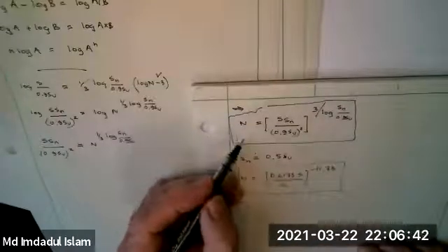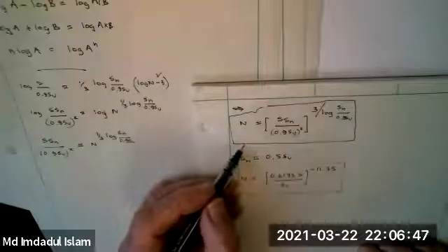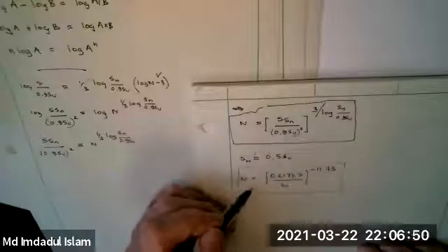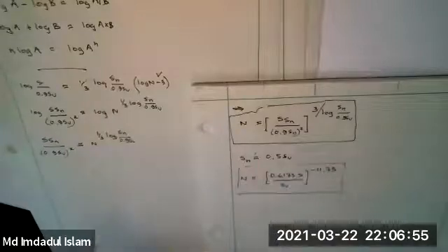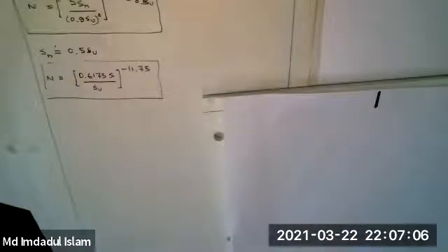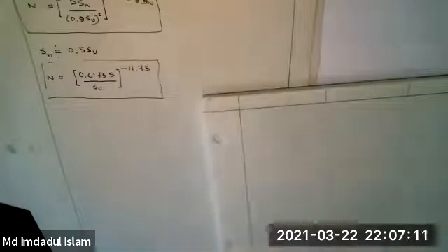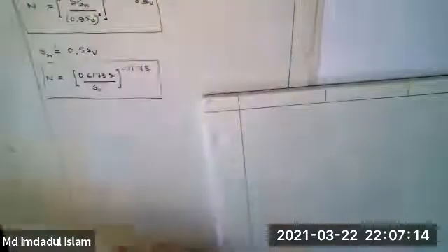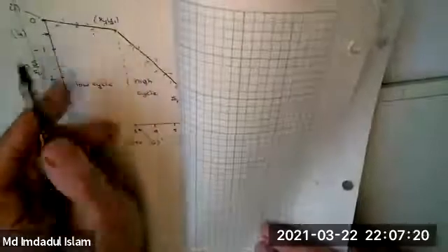When you've got SN, you want to use this. This is more accurate, but SN takes quite a while to test and get to. So quite often we don't have it, in which case you can use that. Now that's all just using logs, and if you haven't seen it for a while, it may look a little peculiar, but this is how you do data reduction. Let me do another one. Let me do low cycle. I'm going to fit this from here to here.